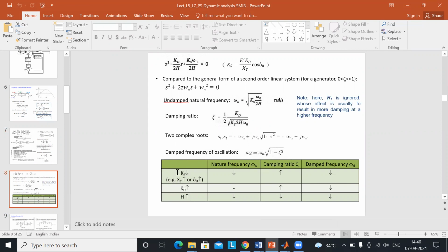So here we had the synchronizing torque coefficient, damping torque coefficient, and the inertia. You see, these are the system parameters, because once you have your generator connected to the line to the infinite bus, that is constant. In the same way the damping torque coefficient, because once you have your load and the load is fixed, it is constant. Same way the inertia, once you have your generators and all the systems intact, everything in position, it is constant unless you add some more generators or you add some lines or you trip some lines. So unless you make some changes in the system, these parameters will remain constant.